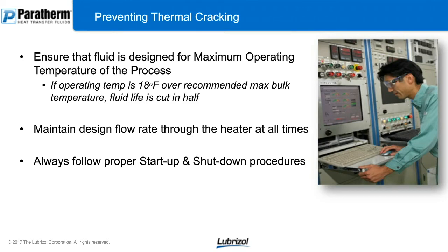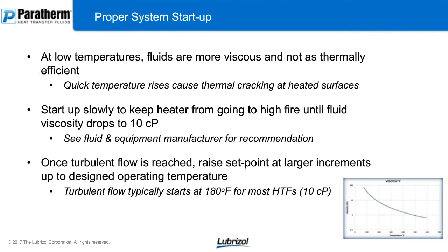You always want to make sure you maintain your design flow rate. That design flow rate is there for a reason. It's to give you proper heat transfer, high enough turbulent flow to move the heat from the heater out to your process. And always follow proper startup and shutdown procedures. So what are our proper startup and shutdown procedures?